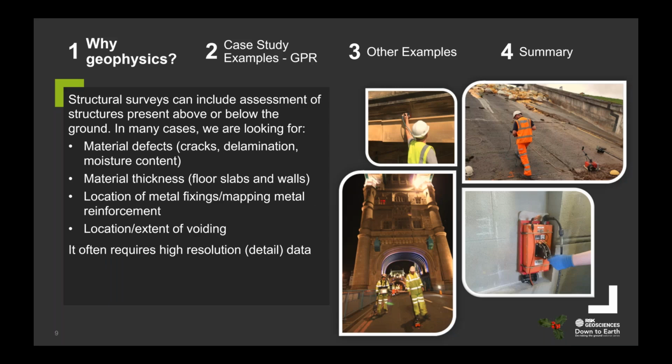Structural assessment is commonly used to look for flaws within a structure. Quite a lot of the time, these flaws are quite small in scale, so we tend to choose techniques that have a high resolution that can show us this fine detail. A common technique we would use for this is high frequency ground penetrating radar. Generally we're looking in the range of 900 megahertz to 2.6 gigahertz.